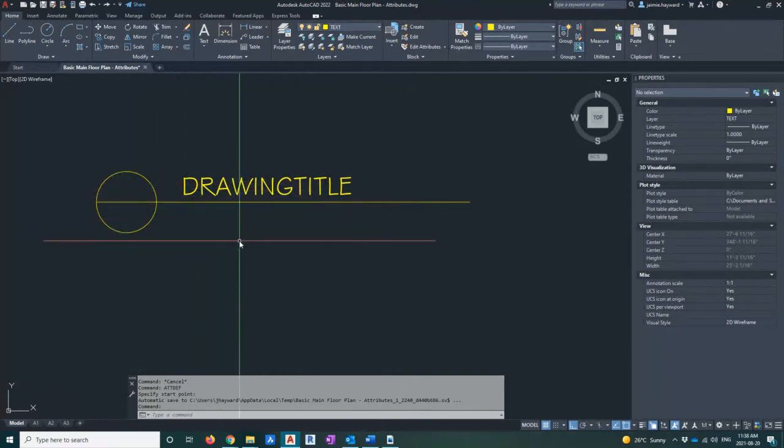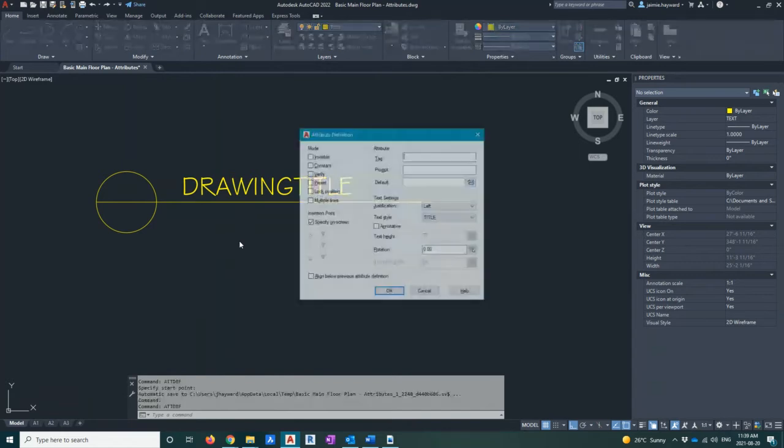For you, I'm not sure. Again, if you're doing a title block, you're going to want to pause this video and sit there for a bit and make all your attributes, because you're going to have a lot of attributes. But if it's like part tag, you're probably going to have 1, maybe 2, who knows. So now's the time to make the rest of your attributes. So I'm going to go ahead and make my next 3, and we are literally repeating the steps. And I'm now going to fill out my next attribute tag for the next spot, which is scale.